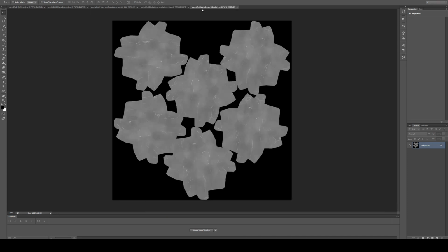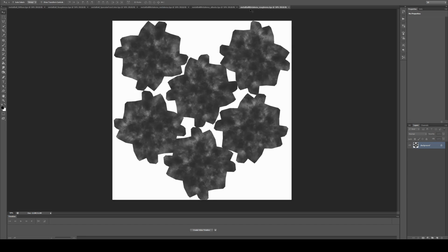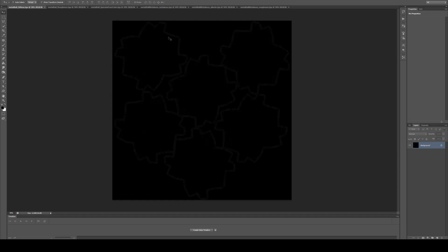The next we have the metalness albedo, and if you switch over to the specular face color, you'll notice that they are the exact same map. So that gives us an indication that we'd actually be able to run this into our specular face color and have it work. We have the metalness roughness, and if we look at the roughness map that we have from the specular workflow, you'll see it's also the same. The only map that we don't have is the diffuse map. So if we look at our diffuse map, what you'll notice is that it is completely black. So essentially any area that is black should appear metal. Now in this model, again, the entire thing is made of metal.